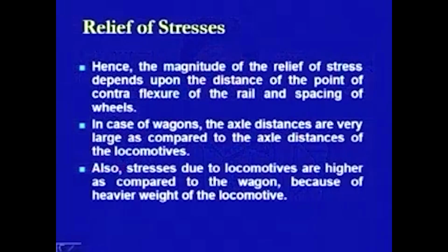So, it means there is a wide range in which the weight of the locomotive varies, but not necessarily on each and every section of the track do all these locomotives ply. Therefore, we first have to identify the types of locomotives which are operating on a section, or which are going to operate, or where there is a feasibility of operation of certain locomotives on that stretch, and then on that basis we can find the heaviest locomotive, and for that heaviest locomotive the things can be designed.